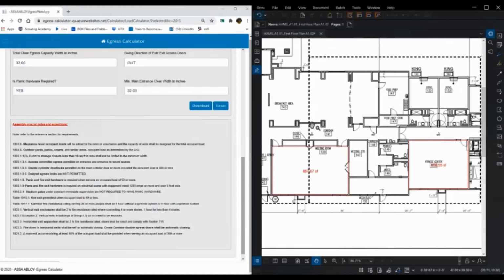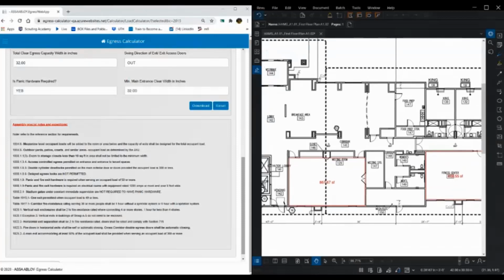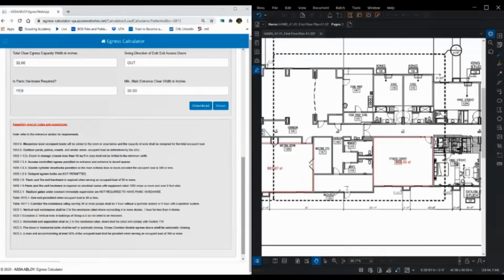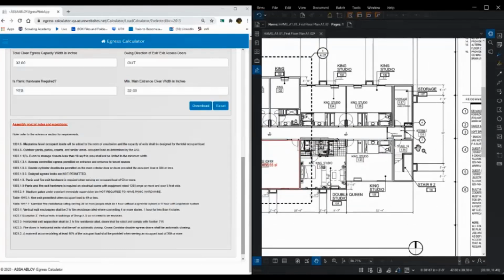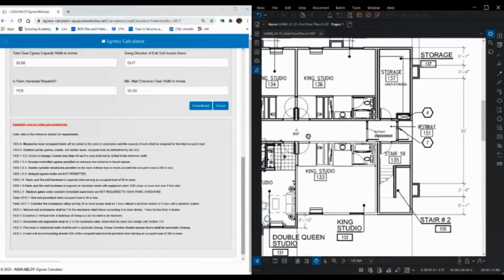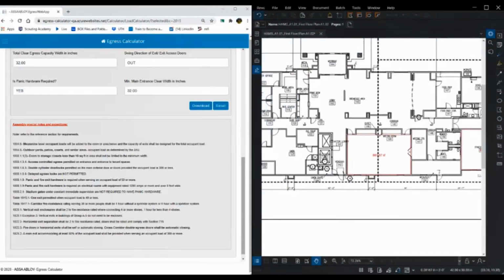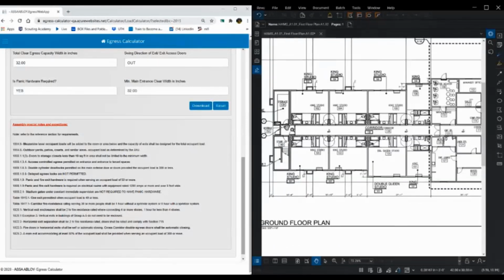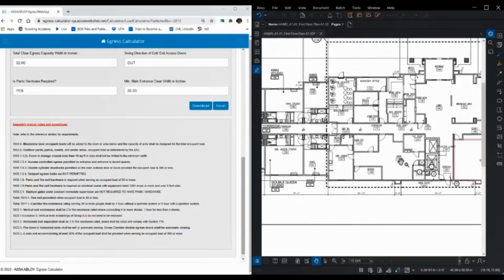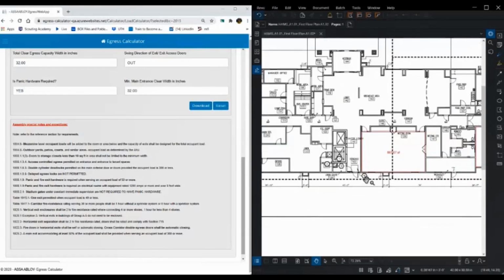We also have this breakfast area, which looks like it's large enough to be considered assembly. So between these two, we definitely have mixed occupancy. This would need an exit device. These doors would need an exit device if they latch. This one for sure because it's an exterior door. And then to keep continuity, these doors on this end as well, even though they don't technically need it because our second exit is this door, this one needs an exit device.